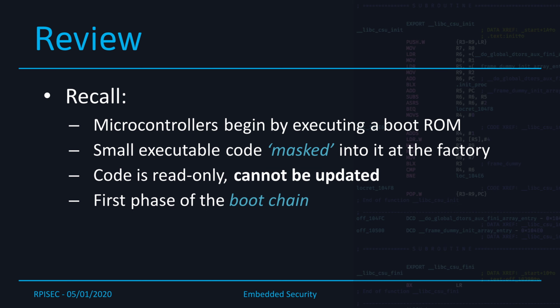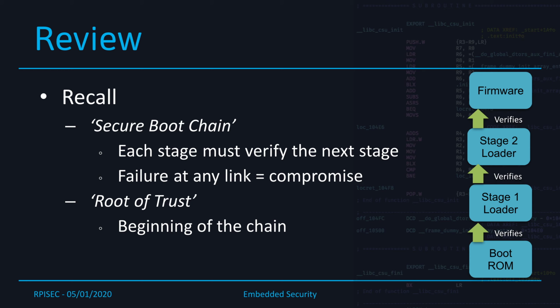So remember that we have microcontrollers, which will begin by executing a boot ROM. And your boot ROM is some executable code that's masked in at the factory. It's read-only and can't be updated, and it's your first phase of the boot chain. And as we boot the system, we're going to be increasing in complexity by loading more and more stages that initialize more and more of the hardware.